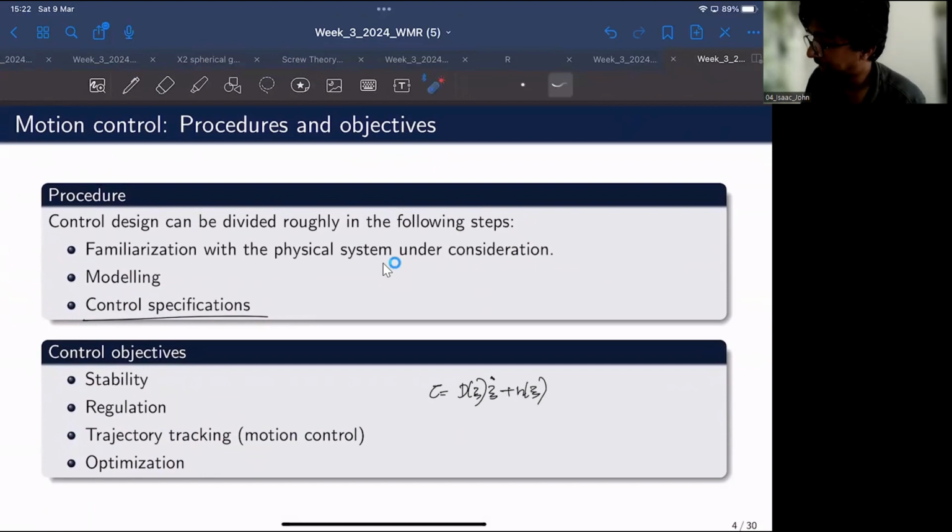As you can see, there is no dissipative term inside. There are no dissipative forces or dissipative terms inside this dynamic model. We haven't considered any of these dissipative forces, maybe friction or damping or any of those sort of things. So as you can see, this system, the mobile robot's dynamic model, is inherently quite unstable.